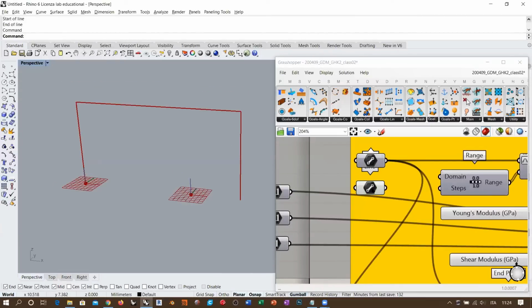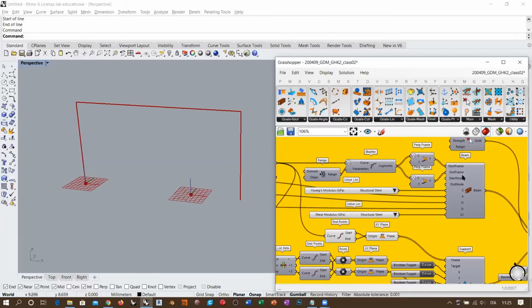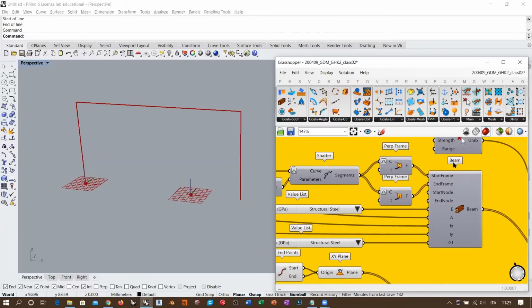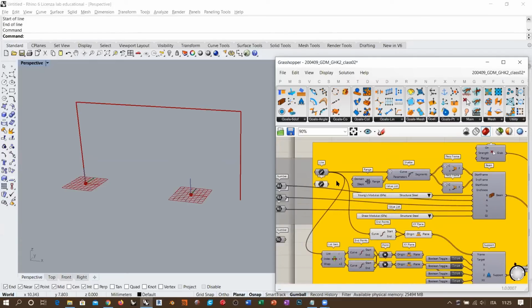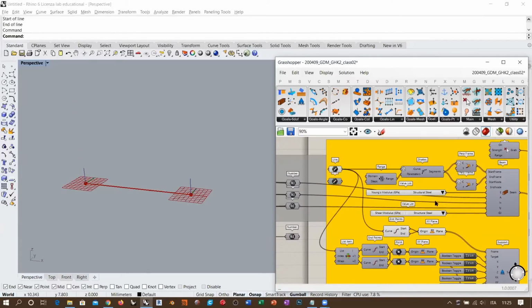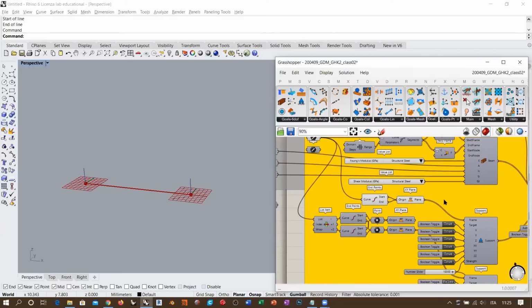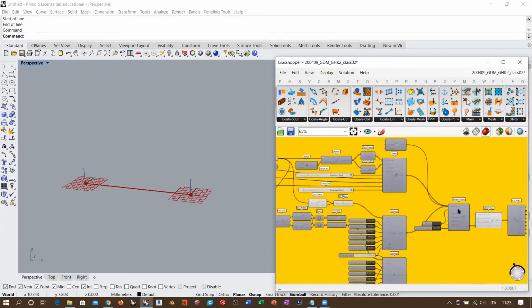We are going to simulate it soon after with this system here. We are going to do this later on. We are going to define two different supports, for example, for the base connection point here, and different supports for the connection here between the columns, let's call it so, and the beam. Now, beam is a general, generic name. With beam, you can simulate both columns and beams. But anyway, we will deal with this in a while, eventually, after the break that we are going to have in a few minutes.